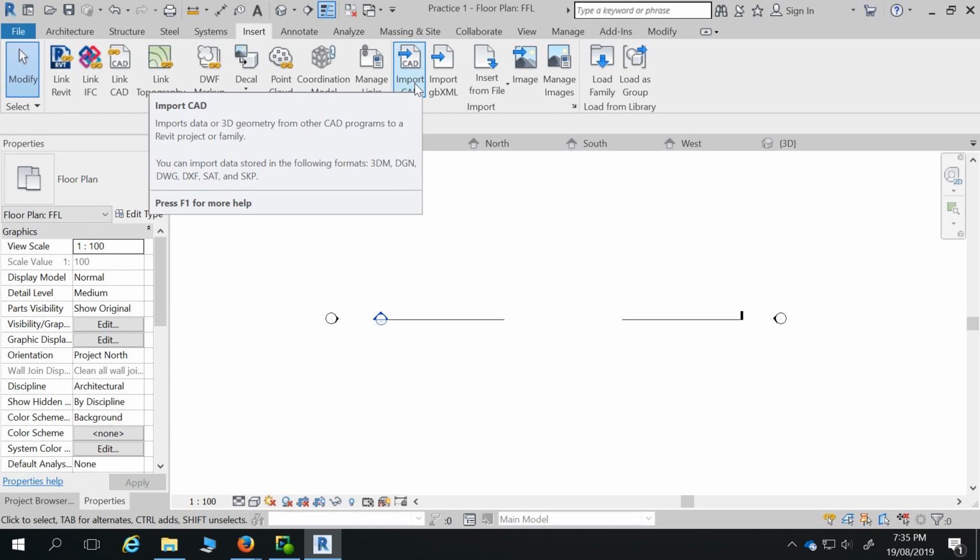If it's linked, it means that it's not completely imported, it's referencing the server. So if it's somewhere at work and we say we're going to link it, it means that if something happens to that CAD file on the server, i.e. someone else wants to update or change it, we've only linked to it. So we'd probably get a message that says the CAD plan's changed, do you want to update it?